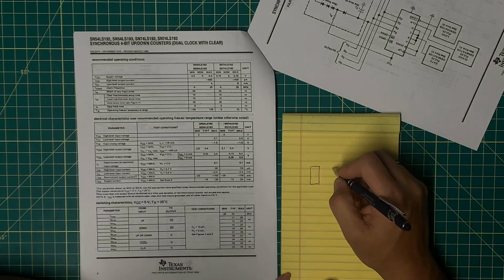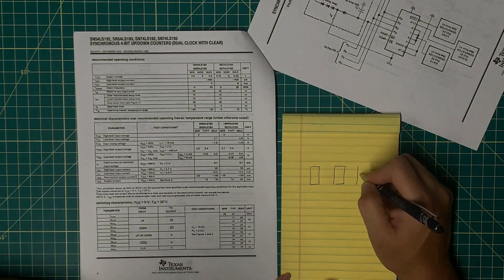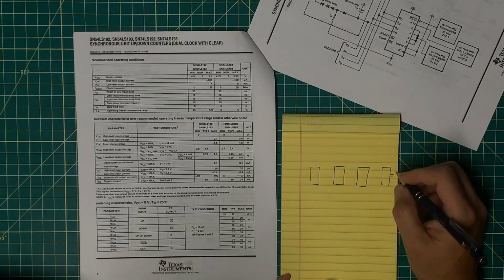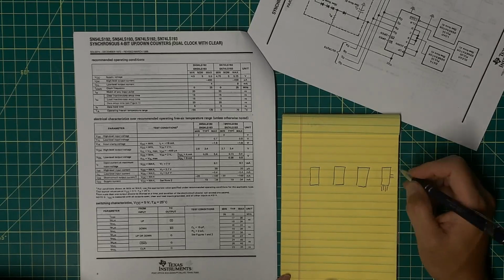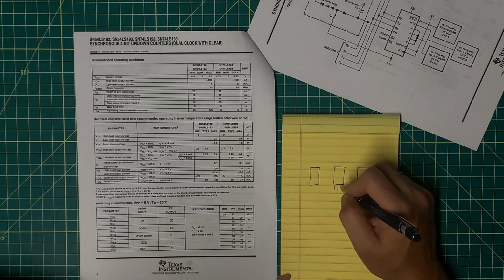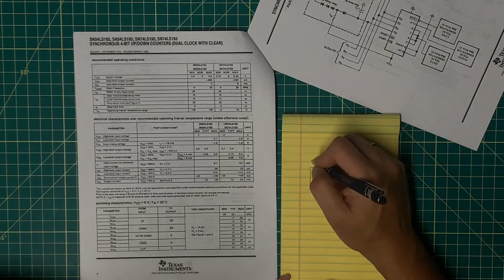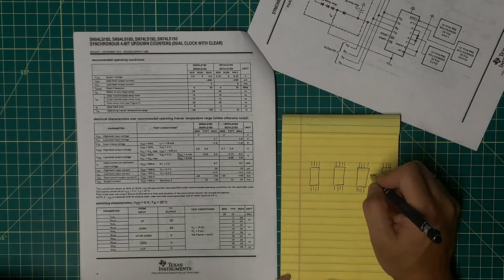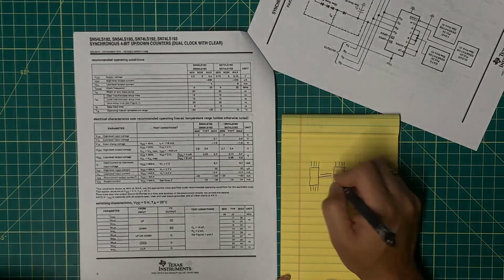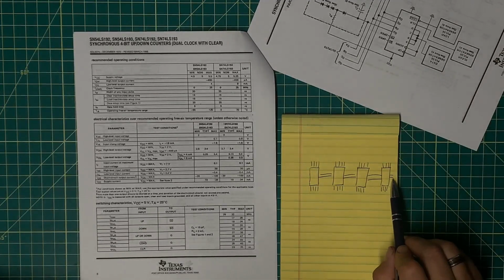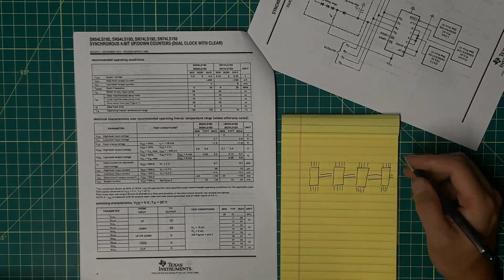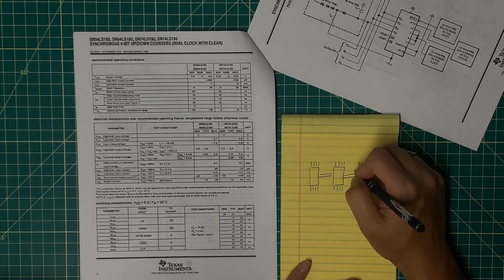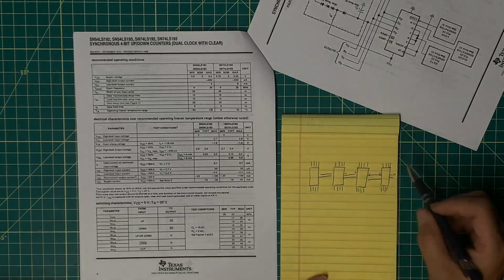Let's start by looking at what my build out actually looks like. And so if I was to lay this out, I've got four ICs here where I've got count up and count down, 4 inputs on each, 4 outputs on each, and then each are tied together such that if I am counting up, and let's just assume that the top line is up, and then I've got the carry to an up, and then carry to up, etc.